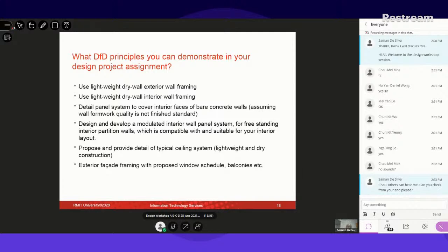And there's another very important reason for that as well. Say, for an example, you design an office tower. Let's say after 30 years or 20 years or whatever that is, all of a sudden somebody acquires that particular property and wants to convert it to a residential apartment. Now, if you have interior drywall, non-load bearing walls, you can strip them very, very quickly and then reuse them, isn't it?